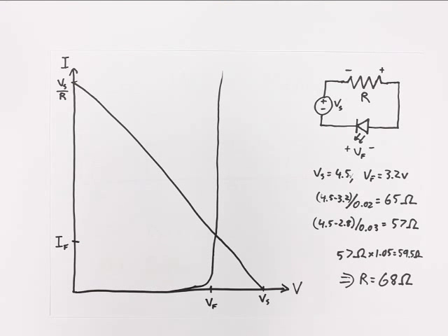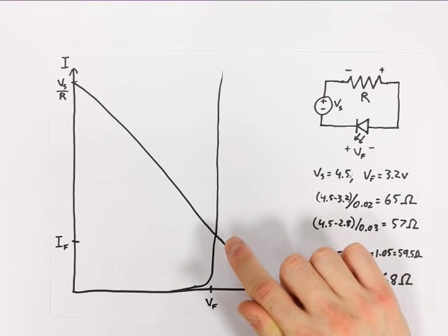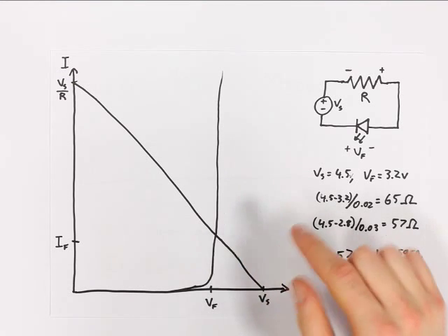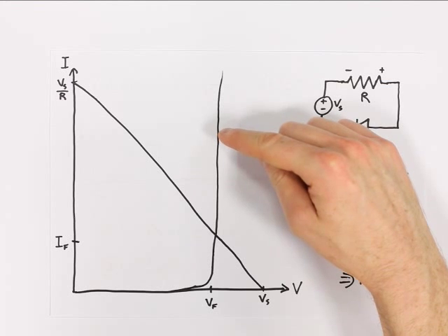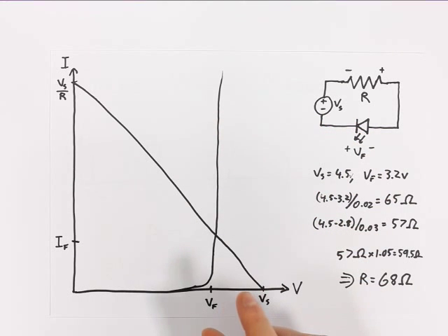So, one other thing I'll mention is when I decided to undertake this project, one of the big questions for me was, can I get more efficiency out of my LED by using PWM? Rather than controlling the current, can I just push an enormous current through it, but only for a brief period of time, and reduce the resistive losses in the circuit by connecting it directly to the voltage source, but cycling it fast enough that I wouldn't blow up the device?